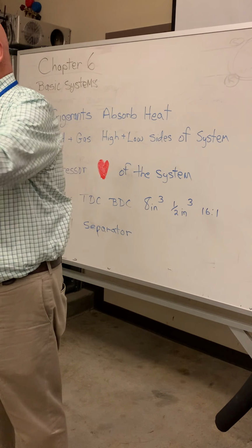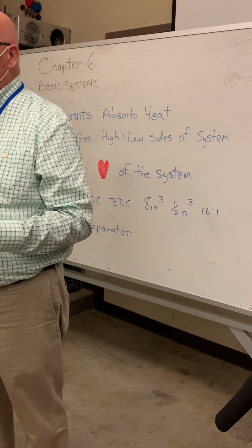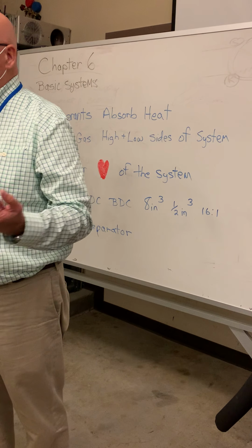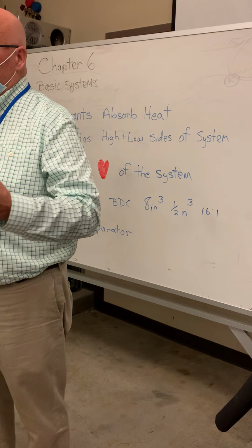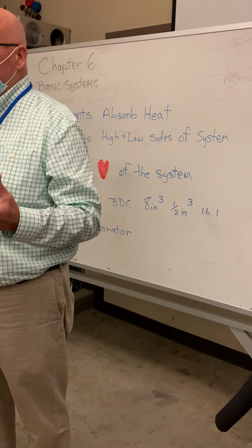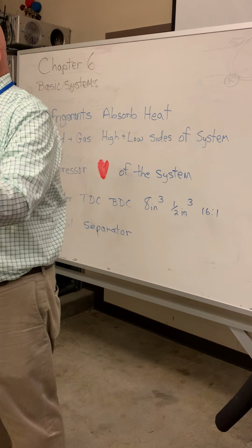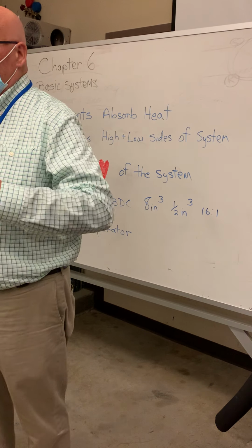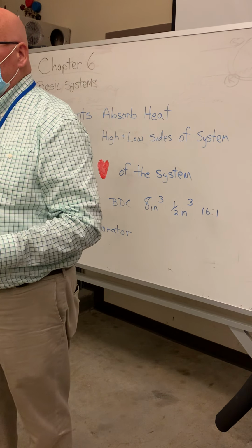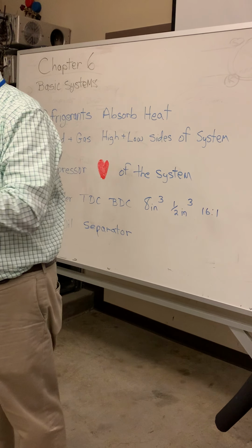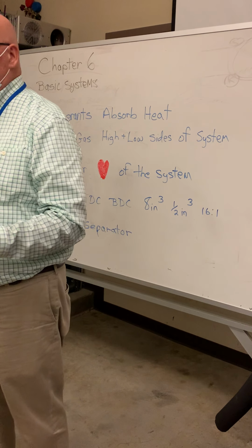They want it to be 40 degrees Fahrenheit so that air coming in a little bit above 75 degrees Fahrenheit will say, whoa, it's 76 degrees here. I'm going to jump inside of this refrigerant and hitch a ride along with it because it's much cooler. So you have a couple of processes that go on for air conditioning.